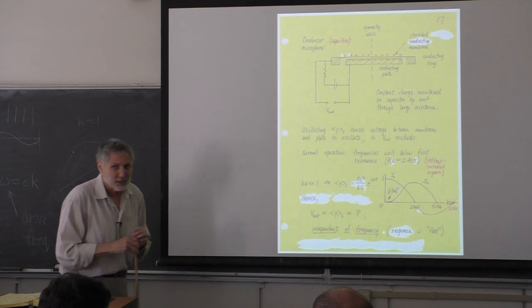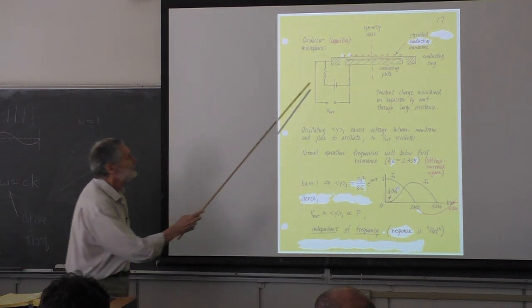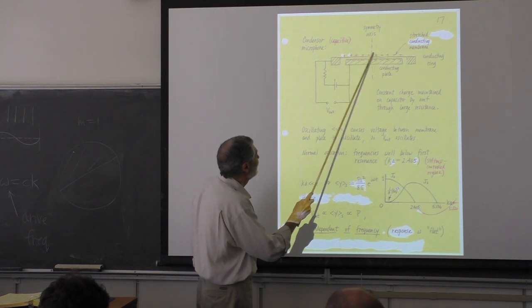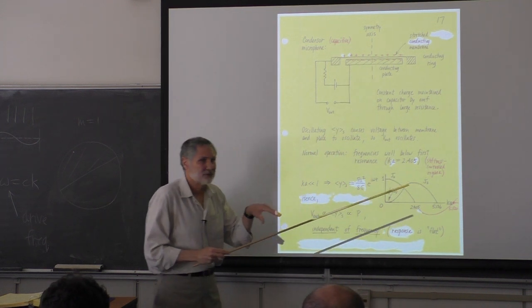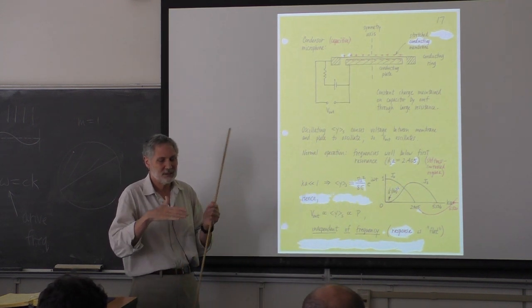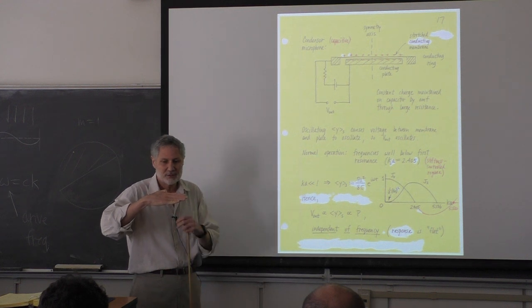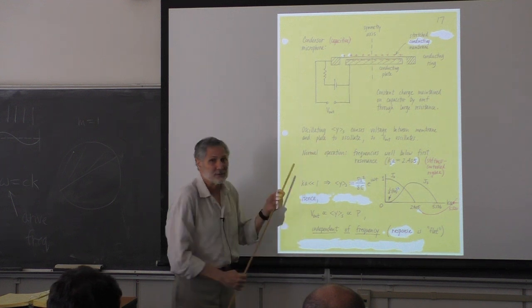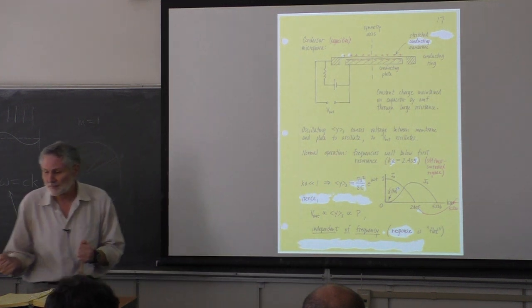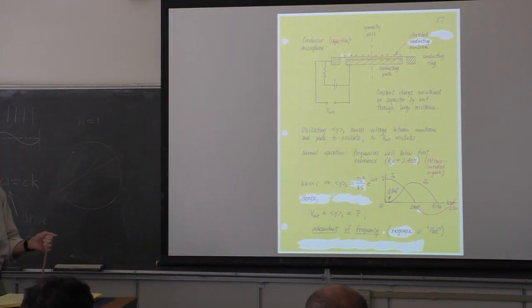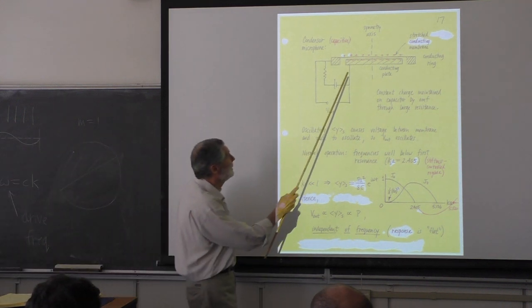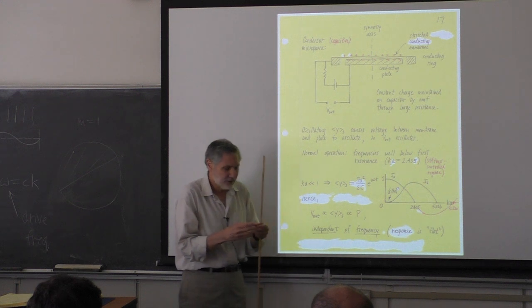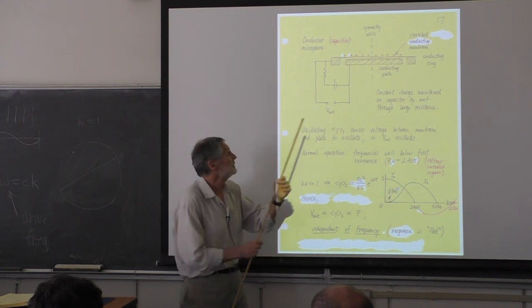Well, the cheap way is to not have this construction, but use an electret material. This is a solid material that is permanently polarized. It has permanent charge here. It's a dielectric, a piezoelectric type material. We'll talk a lot more about that in the transducers course. But here, due to the alignment of the dipoles, there's a slab right here.